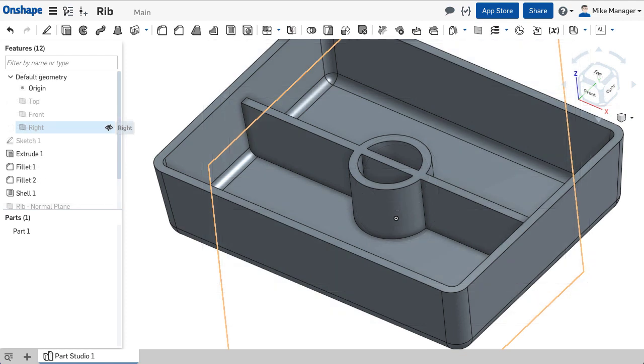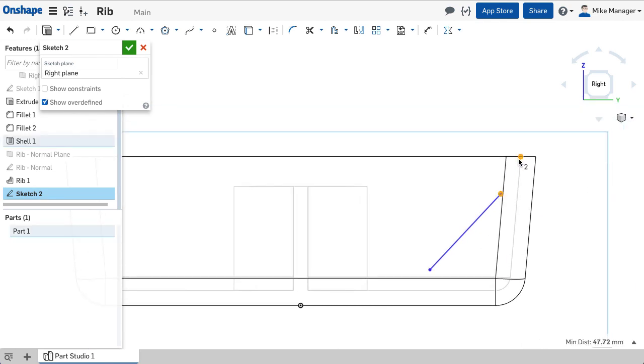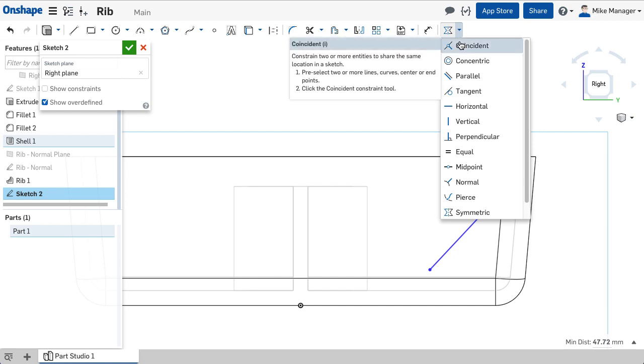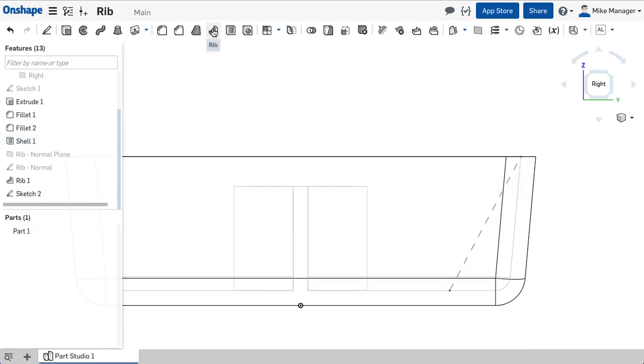In the second type of rib that you encounter, you will notice that you can use the Parallel to Sketch option. This makes it easy to add strengthening ribs to walls that are common in plastic and cast parts with drafted walls. Create a sketch on a plane that intersects the walls that you want the rib to intersect with. You can optionally add relations to the walls so that your design intent is preserved if changes occur to the design later. In this case, adding relations to the walls directly and the corners directly.